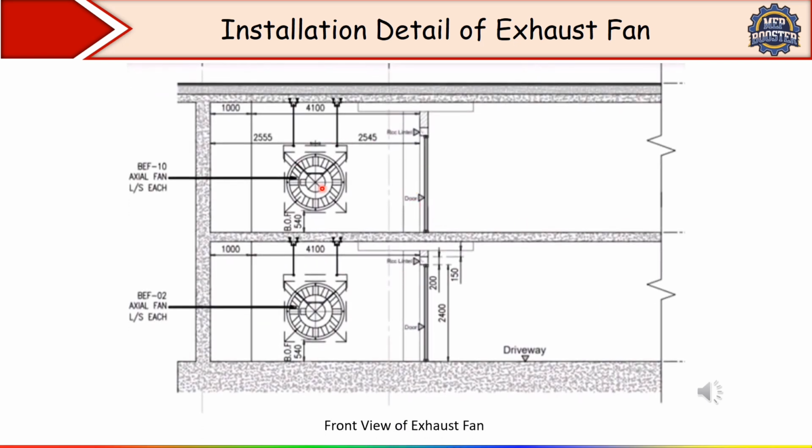This is the front view of the exhaust fan. See how it looks. All detail is given. See from the wall to this fan how much distance we have to maintain, and at what height we have to install this fan from finished floor level: 440 mm. Then the hanger detail is also given.